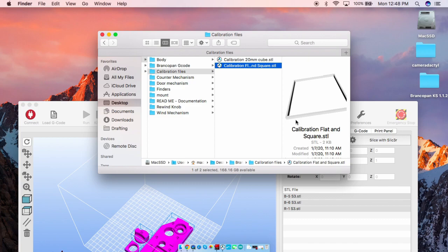While it's printing this, I like to screw the adjustment screws on the bottom of the print bed at each of the four corners to make sure that it's printing a nice even line. I might restart the first layer a couple of times if it takes me longer than the first layer to get that dialed in. Usually it doesn't now, but the first time maybe I would have had to print it 3 or 4 times before I got everything perfect. There's certainly the piece of paper method, and you can watch a lot of YouTube videos on how to calibrate and level your print bed. But for me, this is the nicest file that I've used to do that.